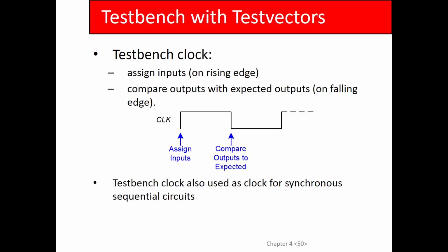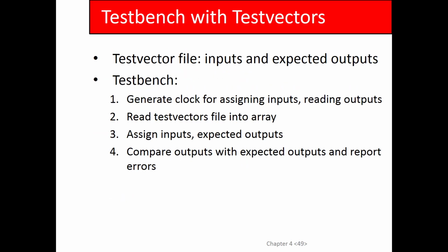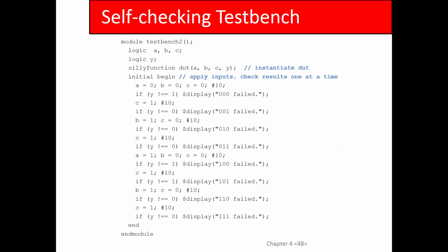In the example they give here, one of the problems is that you have to set all of the inputs and the expected outputs inside the Verilog. It would be better if you could decouple the Verilog code from the actual test cases that you want to test. That way, if you want to add test cases, you just add them to a file. You don't have to go in and worry about introducing a bug in your Verilog or worry about having to type all the extra text to implement the if statements and the prints and all that kind of stuff. You guys with me?